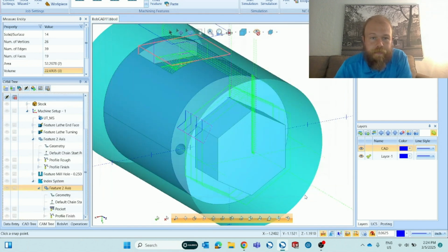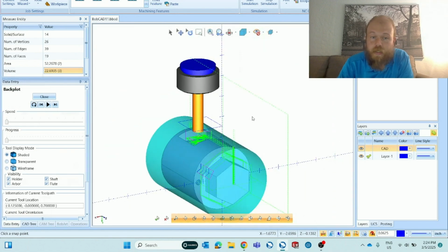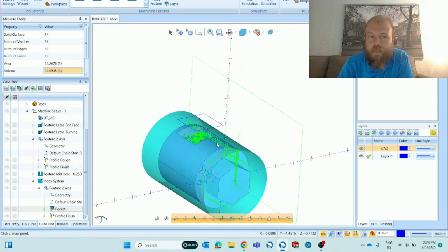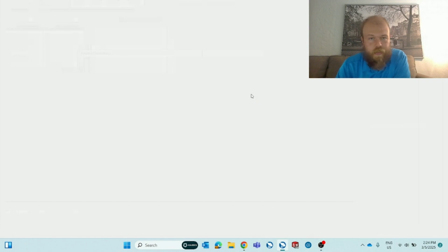So again, we've got this tool as tool number 10, the correct mounting orientation. I hit compute. The toolpath looks good. The backplot's going to look good too. I just want to make sure that simulation will work correctly for us based on the machine I have selected as my BobCAD, 1 turret, 1 spindle machine. It actually works for us. Cool.